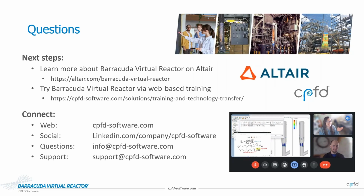What I want to point out is that Barracuda Virtual Reactor uses a 3D MPPIC, multi-phase particle-in-cell method. I point that out to make a distinction between it and DEM. DEM is going to look at where each particle contacts another particle and then compute the bounce. What Barracuda does instead is it handles that through various models. I think the person who asked that, by the way it was phrased, understands that.